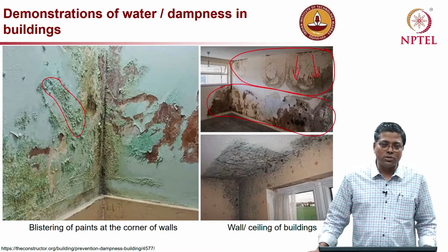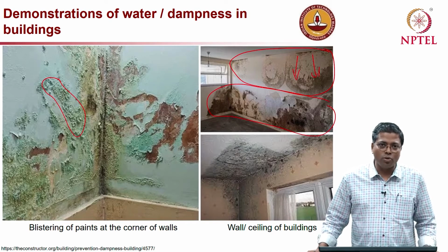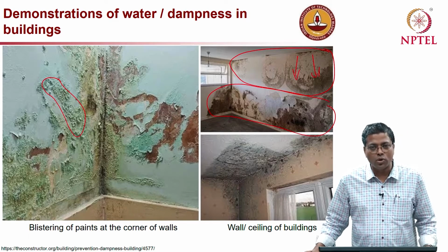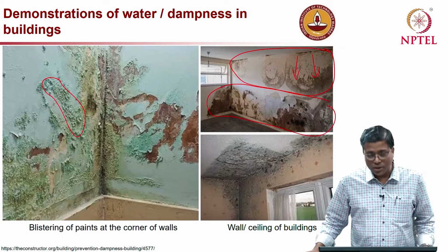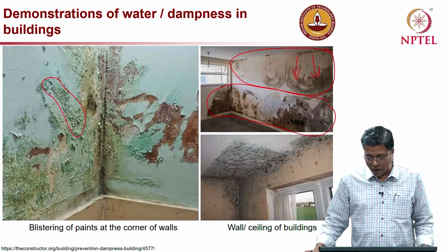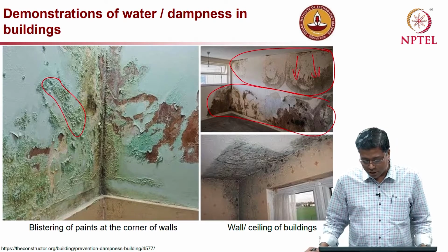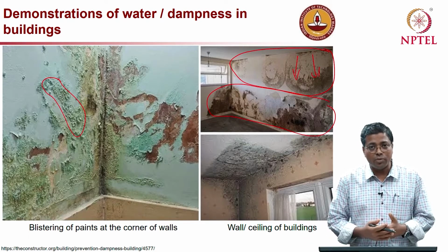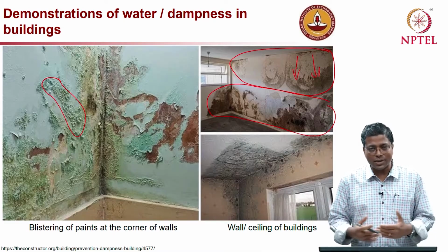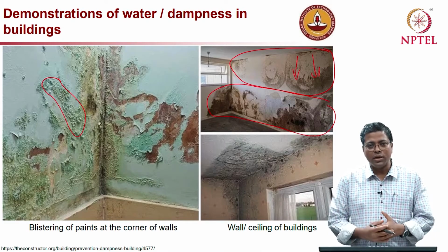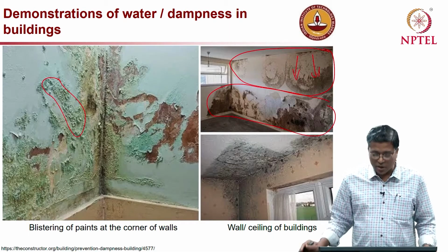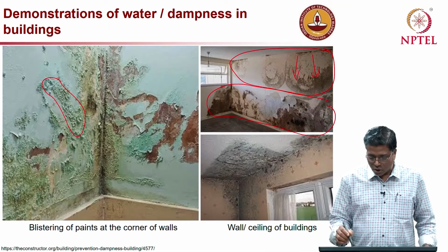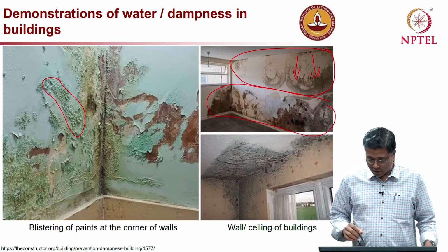Mostly it is because of either a bathroom or some pipeline which is probably corroded, or water leaking from concealed pipes, or whatever the source may be. It could even be just a roof element above: rain water gets stagnated around the corners and then seeps into the walls, and it is manifested as shown on the top right corner of the picture.